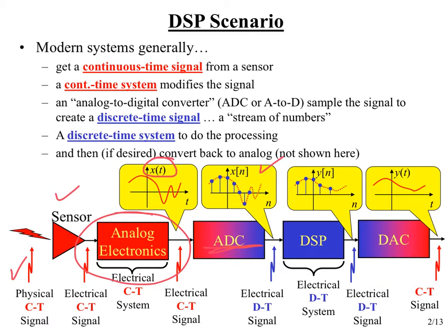And you'll notice here that we are no longer indexing those by time. We're indexing them by an integer, n. So it's just a counting index. And you'll also notice that we think of the plot as those blue dots with stems. So it's a stem plot. And there is nothing in between them. On the plot, I show a red dashed curve to show where the continuous time signal exists. It's not really there at this point. That's just showing us what was there at the input to the A to D converter. So that is our discrete time signal, and we index it by an integer.